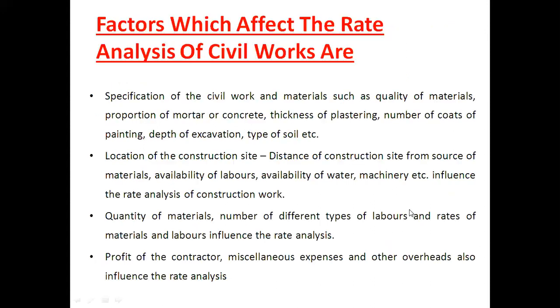Now the next part, the factors which affect the rate analysis for civil works. As far as our construction industry is concerned, which factors will affect the rate analysis? First is the specification of the civil work and the materials, such as quality of the materials, proportion of material, mortar or the concrete, then thickness of plastering, number of coats of the paints, depth of excavation, type of soil. Okay, some examples I have just given.